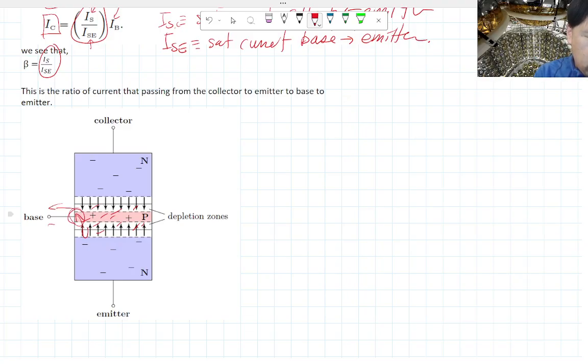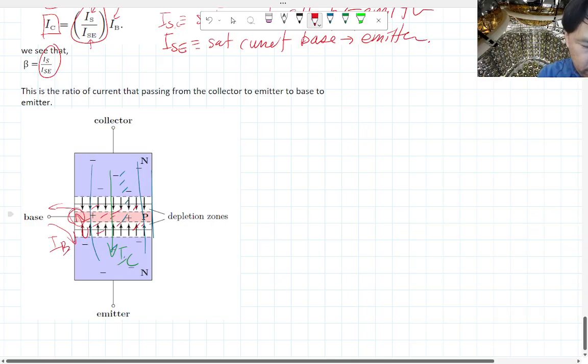In other words, the regular current flows out of the base into the emitter, where the majority, meaning a factor of 100, of the electrons are flowing in from the emitter into the collector. In other words, using the sign convention of positive charge as the current, we have a much larger current from the collector and a much smaller current from the base.